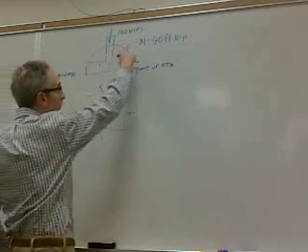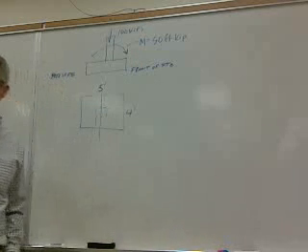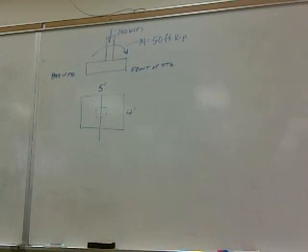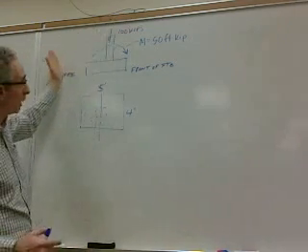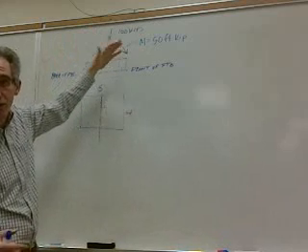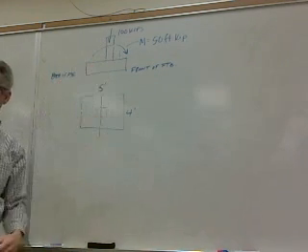And then the footing is also subjected to 50 foot-kips of bending moment, and the 50 foot-kips of bending moment might be coming from a wind load, or it might be coming from soil pressure. It could be coming from a lot of different places, lateral loading that creates a bending.